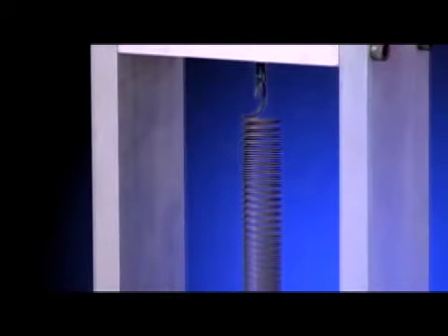We describe what the spring is physically. The spring has the name spring because its main attribute is springiness. So I'm going to assume that this spring is what we call a pure spring. Now, a pure spring is fictitious. It doesn't exist. But it's an essential building block in physical modeling, in this case, modeling mechanical systems. A pure spring has springiness and nothing else. No mass, no energy dissipation. It's not real, but it's a building block that I can use to capture that attribute of compliance, springiness in the mechanical system.